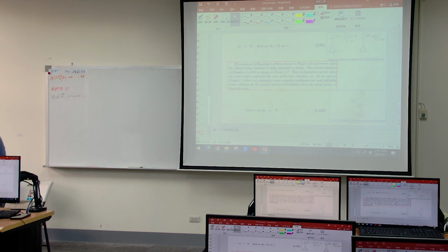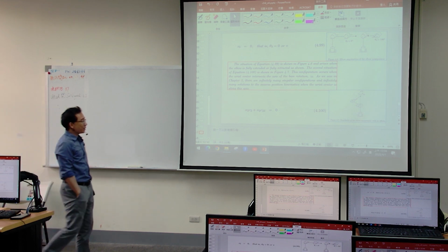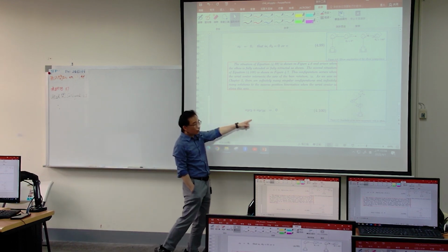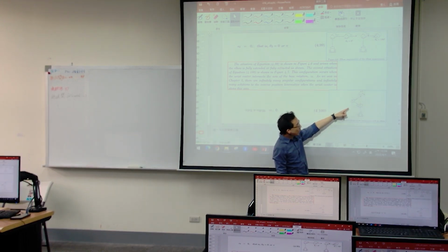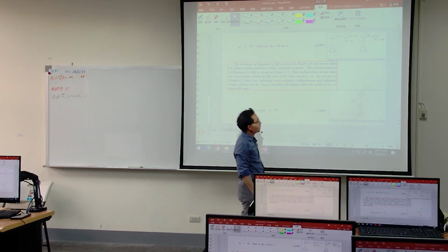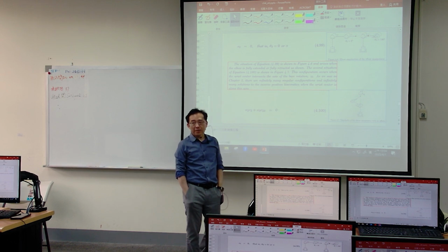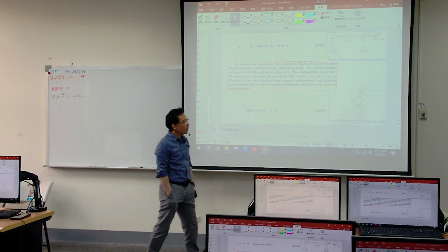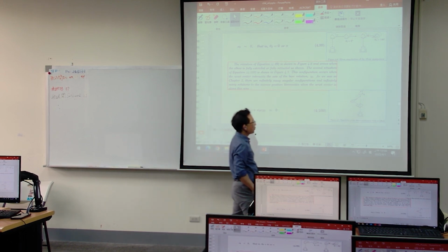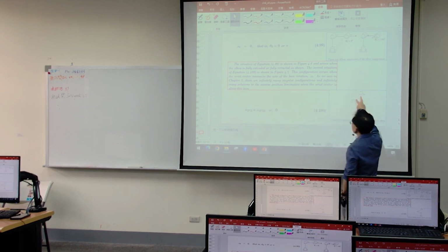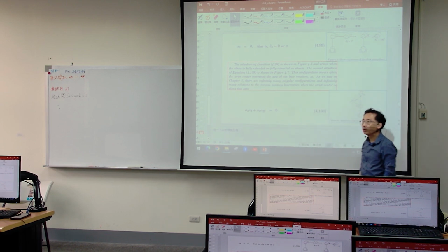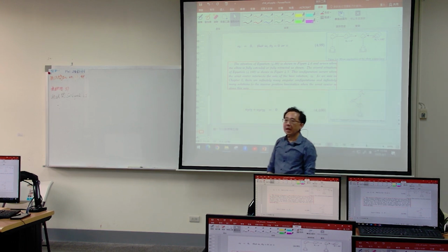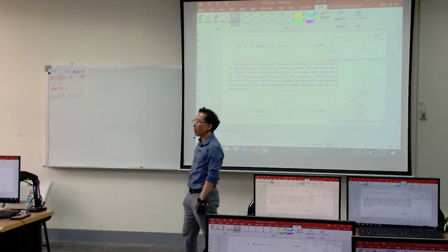You need to understand what C23 is. That is the posture like this one, the end of arm 3. I'm not sure about the length, but once it collides with joint 1, it is another case of singularity.